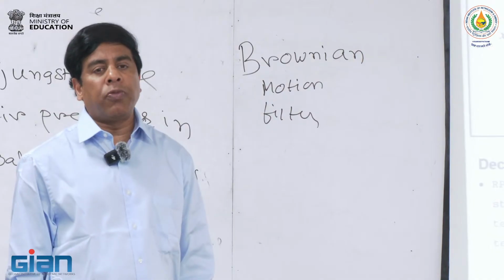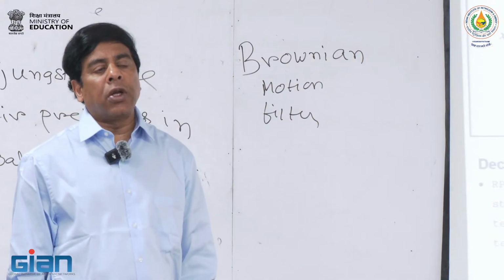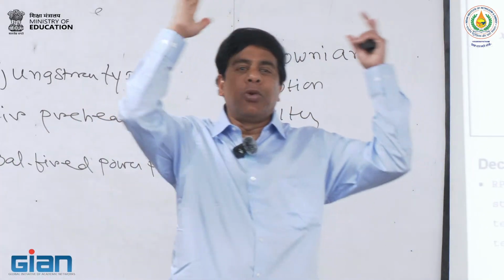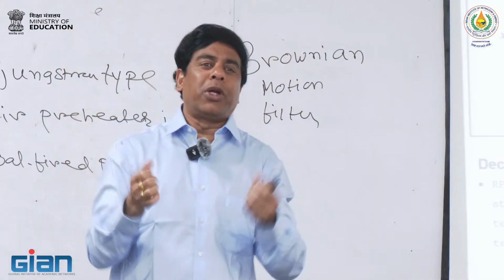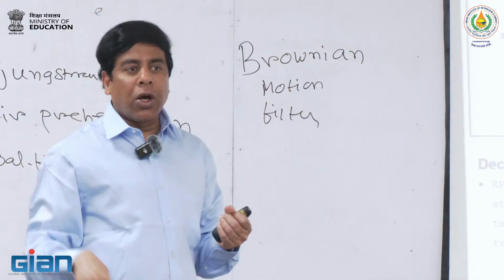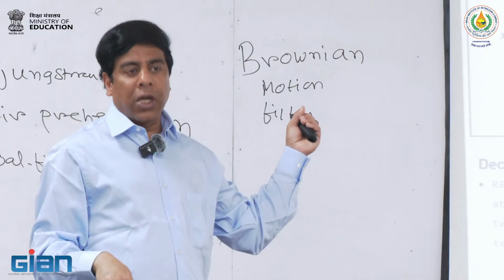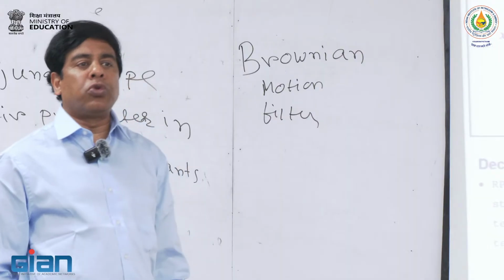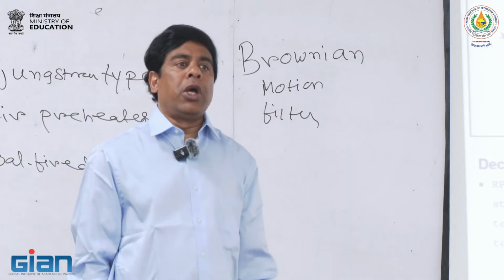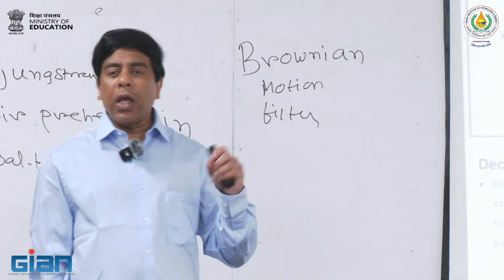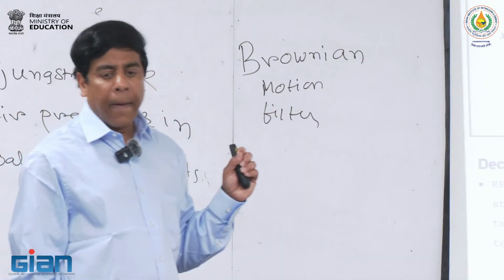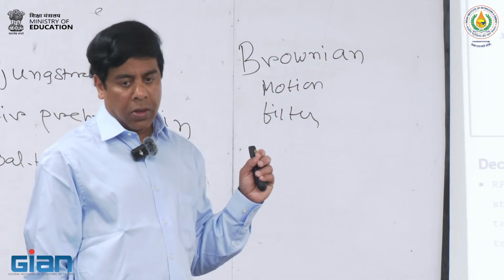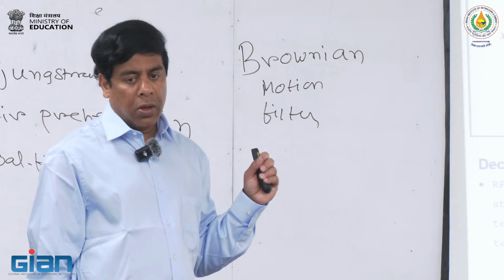I'm not sure you are familiar with many of the refining technologies, where at the top of the reactors, most reactors have a filter, a cage type of filter, and maybe two fine layers. During shutdown, people will take those filters out, because there is some unknown material. It's not expected to show up, but it will show up. You take it out because you do not want it getting into the catalyst bed. Once it gets into the catalyst bed, it's a difficult problem to solve, so you have to take it out before it enters the bed.